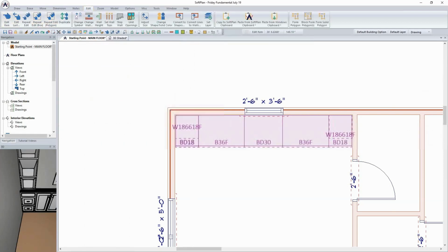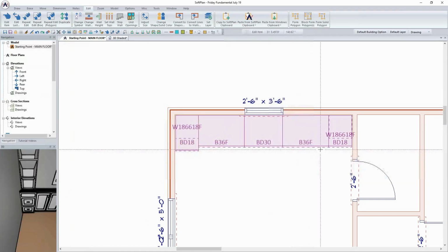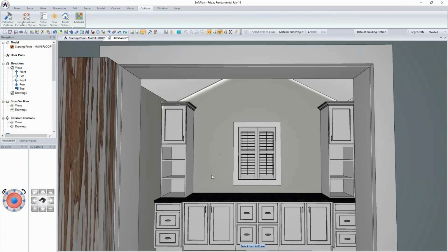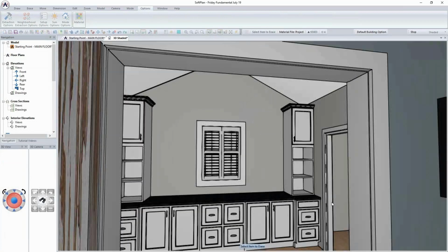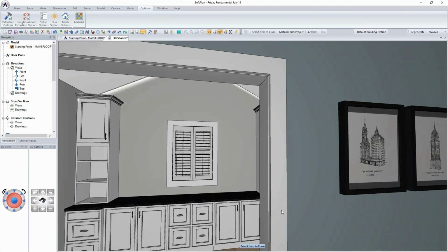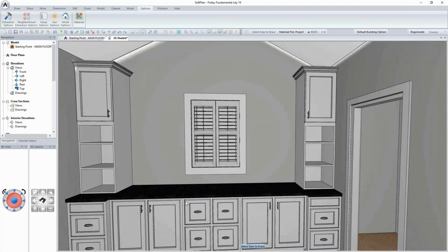And so in this case here, I could edit this drawer cabinet down here at the end, and I could go into that specific cabinet and just override the depth, and let's just make it a little bit deeper, and I'll do the same thing down here with the repeat edit. So as we're taking a look at it, we're actually bumping out the drawer cabinets on both ends, just giving it a more visual definition as far as that's concerned.